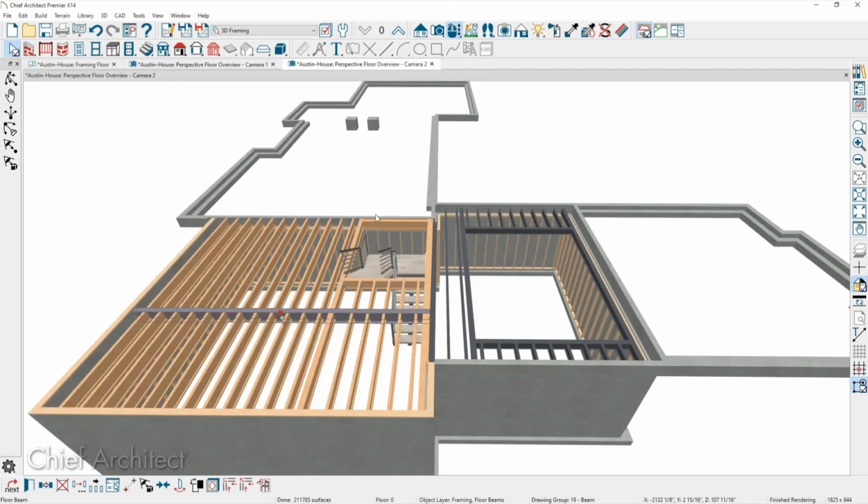Like a footing of some sort? Yeah. We typically will drill a 12-inch pier with a 36-inch bell on the bottom of it. Sure, so you've got more bearing surface. Yeah, so you can either use the footing tool, or you could draw that as a custom polyline solid and add it to your library, and then multiple copy that.